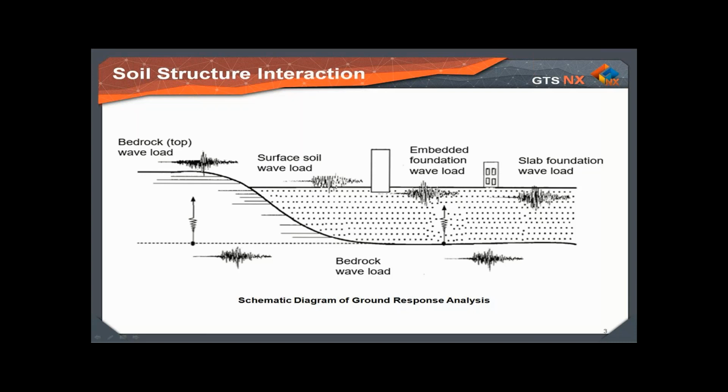The ground displacement, in turn, is largely influenced by the dynamic properties of the ground and its modeling method. The ground exhibits completely nonlinear behavior depending on the strains developed in the ground due to the dynamic load. It is therefore important to closely examine the nonlinearity of the ground relative to strains.